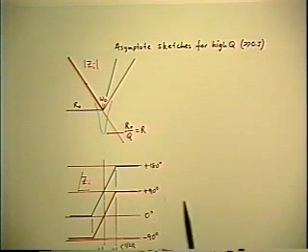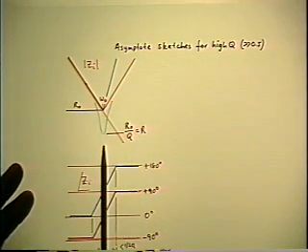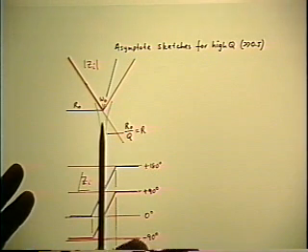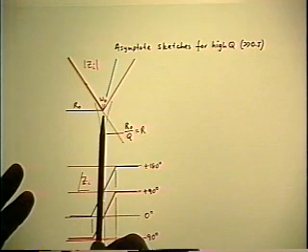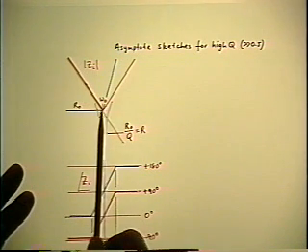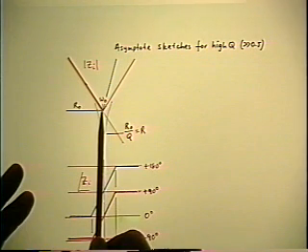So if you consider the same L and C, but a varying Q resulting from a varying value of the series resistance, what happens is the Q gets smaller, this minimum rises, but the asymptotes stay in the same place. So the minimum would get bigger, and if Q is 1, the minimum would actually go through that asymptote intersection.